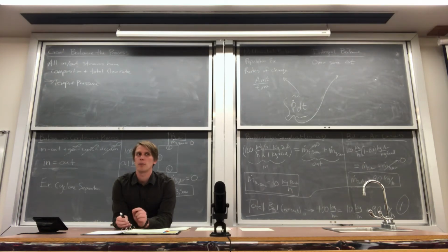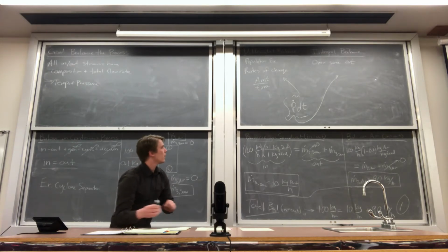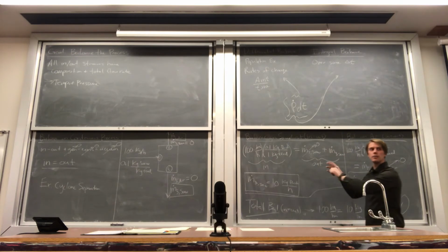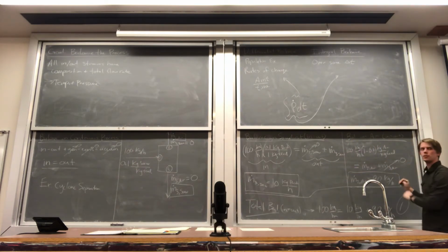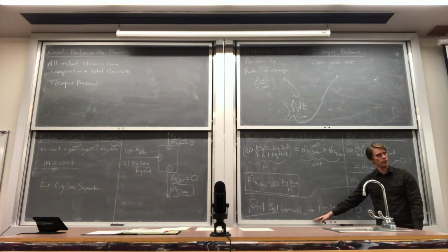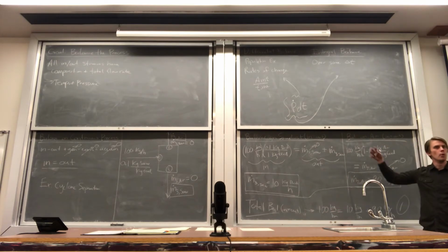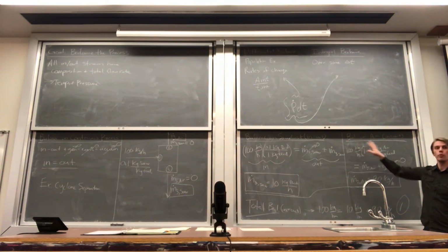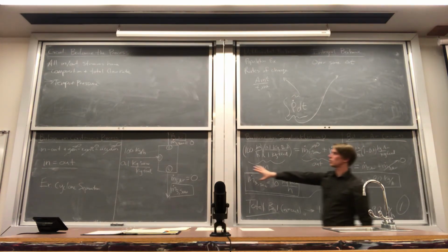But when things get a bit more difficult, you may find yourself in a scenario where you write out one species balance, two unknowns. You write out another species balance, two unknowns. You write out the total balance, 2 unknowns. Right? So you may find yourself in a scenario where you have multiple equations with multiple unknowns that you can't solve in this really simple, straightforward manner. But the strategy that you will be using throughout the entire class, whether it's mass balances, energy balances, thermodynamics, whatever the case is, this is going to be the starting point.